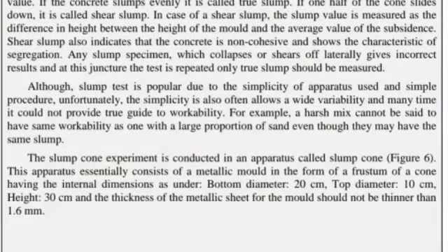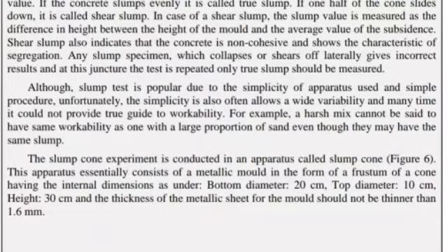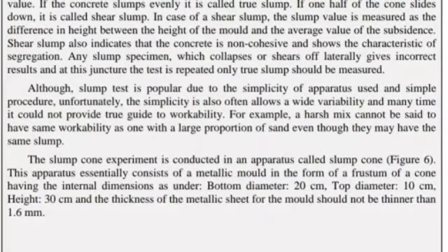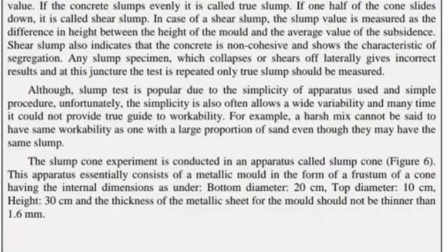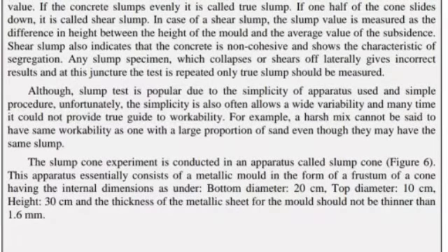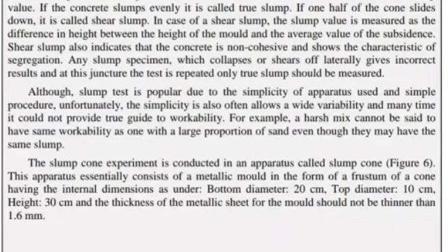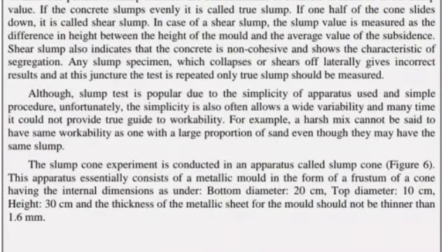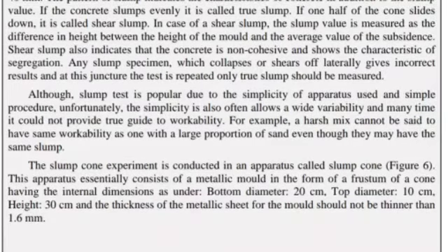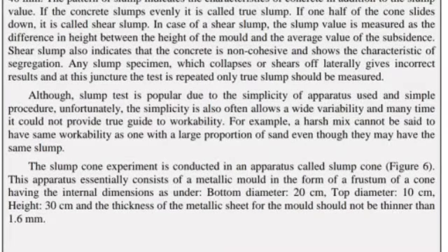Although slump test is popular due to the simplicity of apparatus used and simple procedure, unfortunately the simplicity also often allows a wide variability and many times it could not provide a true guide to workability. For example, a harsh mix cannot be said to have the same workability as one with a large proportion of sand, even though they may have the same slump.